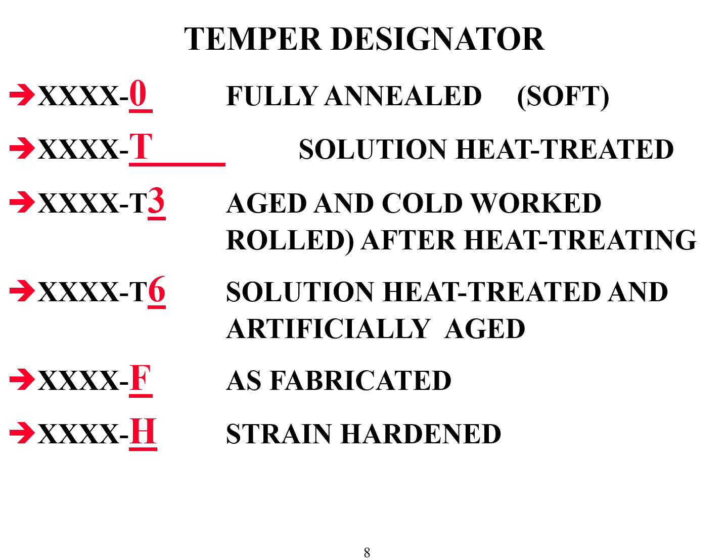Many times we desire the metal to come in that way so that forming and bending operations could be done with tighter radiuses. More detail can be formed into the metal without it cracking. Fully annealed material is soft. It's much easier to handle. Usually, we would take a fully annealed piece, do complex shaping, and then we're going to do one or two things after that. It could be sent into heat treat to fully harden it after that, or sometimes the cold working hardens it enough that it's good as it is.